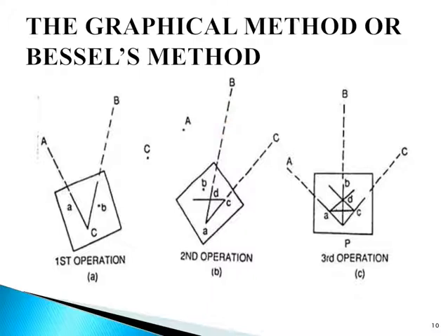Again the alidade is placed along the line AC and the point C is bisected, and the table is clamped with the alidade touching point A. Point B is bisected and a ray is drawn. So these 2 rays are drawn. Third operation is here.